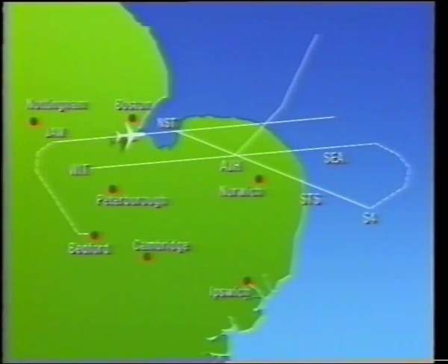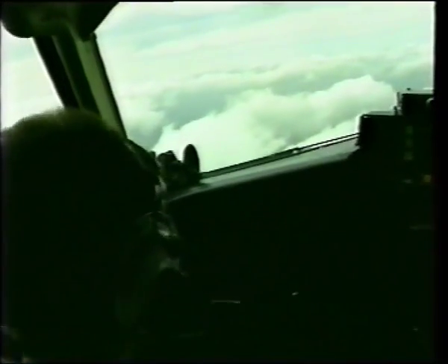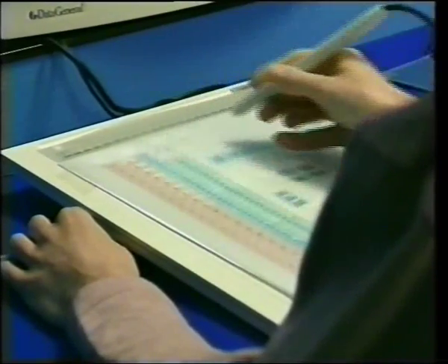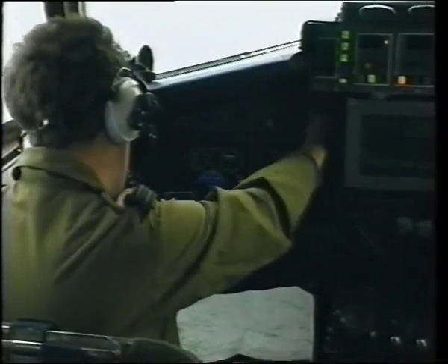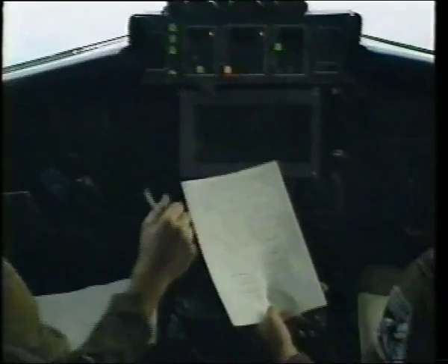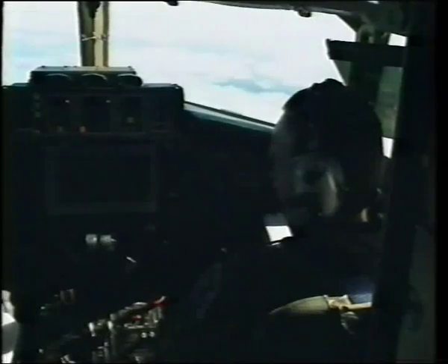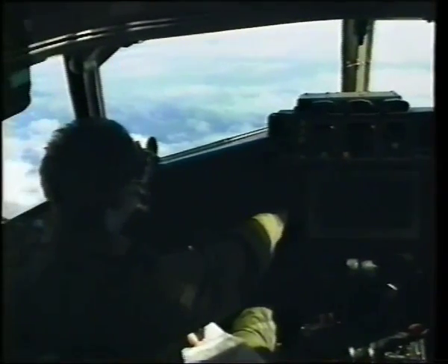Having now adopted for Scenario 1 the call sign Nugget 1, we will concentrate mainly on the use of the EDD screen. Still utilizing conventional RT, respective instructions are first radioed to the pilot and acknowledged in the normal manner. At the same time, they are inputted via the digitizing tablet. Okay, I'm replying to her instructions. I'm also dialing these settings on the autopilot. They're going to the data link processing unit and being downlinked to her on her screen.